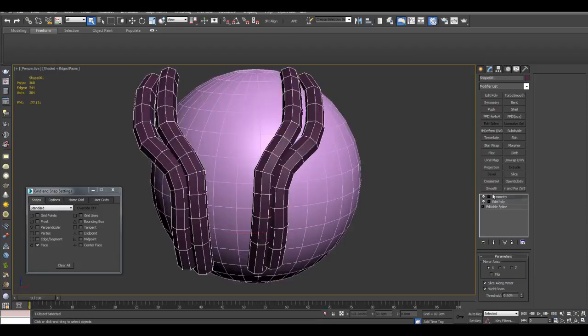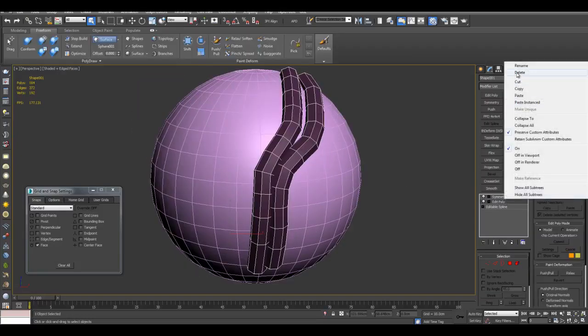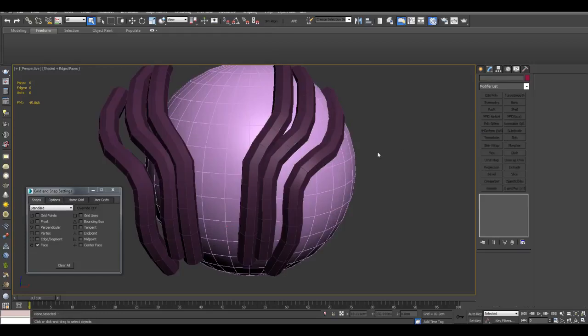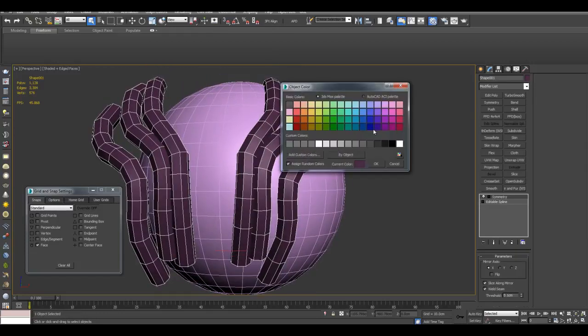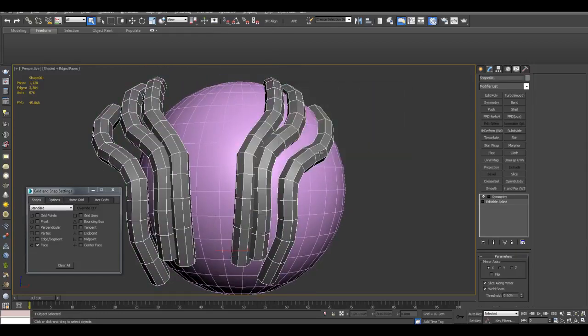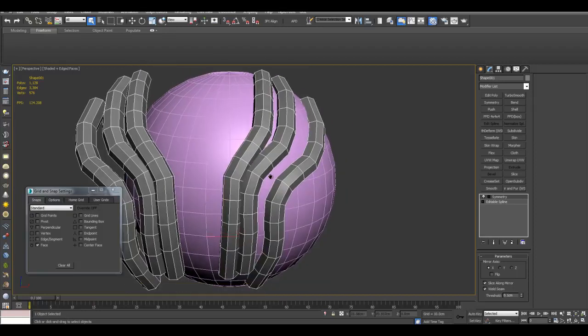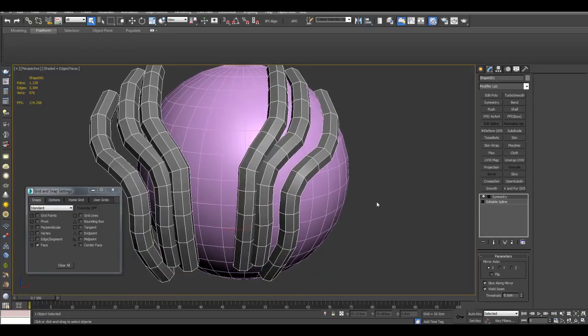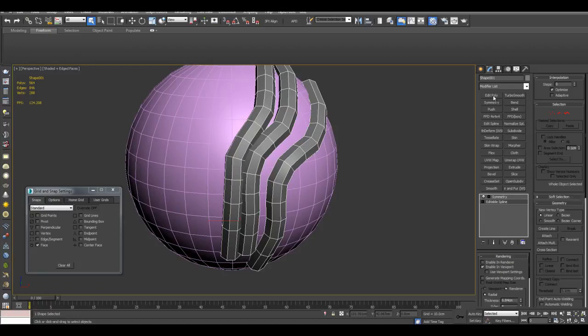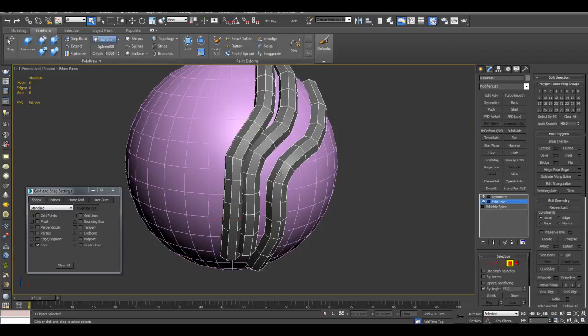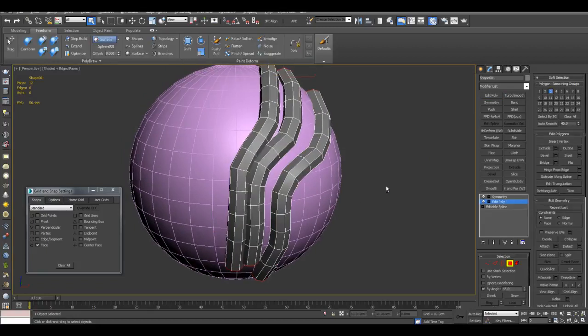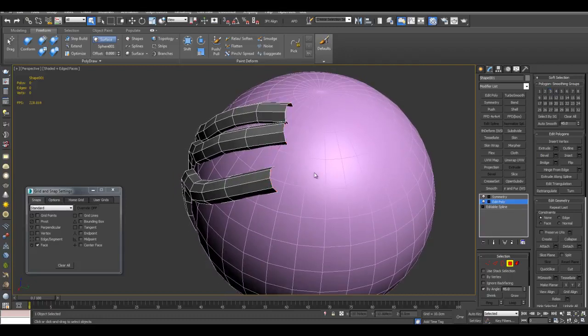And now I'll select this object and just delete edit poly. So we've got this back. So let's say that I just give this a light gray material, and I want to split off the center of this to make it a different object, a different material. So first thing I'll do is just apply edit poly, by angle, select, Control I, and delete.